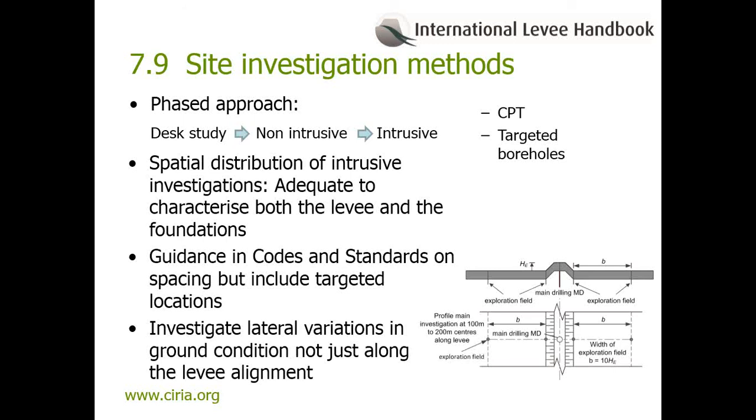These can then be reviewed as the investigation progresses, allowing the supervisor to schedule slower, more expensive and possibly fewer boreholes and in-situ tests that start at a slightly later date in the GI program, adjacent to targeted CPTs to maximize the information obtained, investigate ground anomalies, and develop site-specific parameter correlations of soil properties with the results of the CPT soundings.